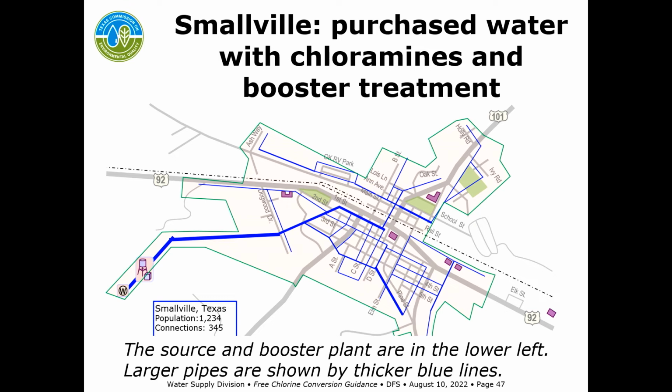And this is their distribution system, and it shows, if it's a city, maybe they have customers outside the city limits. That boundary, that pressure plane boundary, needs to include anybody who's outside of your city limits. City limits isn't the same thing as your service area necessarily. Through the distribution system, the thicker blue lines represent larger diameter pipes. And so where you see the thicker ones, kind of the trunk mains, and then the smaller lines out to the customers.